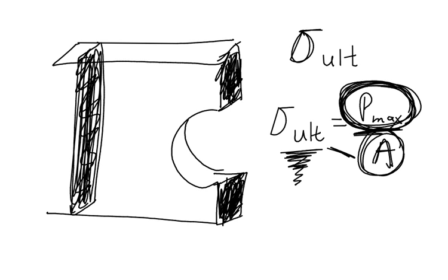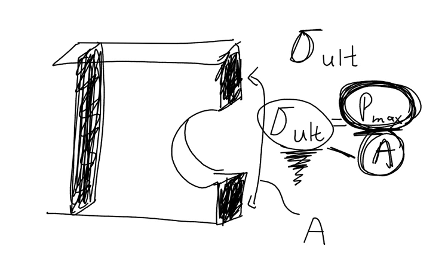So that's fine, people made that determination. They went through that reasoning and said, okay, I'm going to take this as my area, and then I just multiply that area by my sigma ultimate, and that should be the largest force that I could apply to this plate. Guess what? When people applied that value of P max to the plate, the plate failed well before they were able to get to that force. It was failing much sooner than predicted. So why is that?